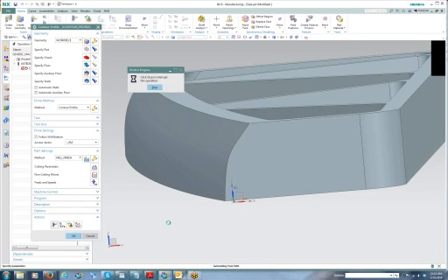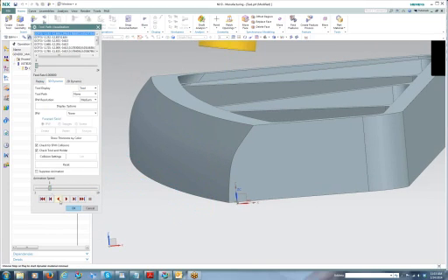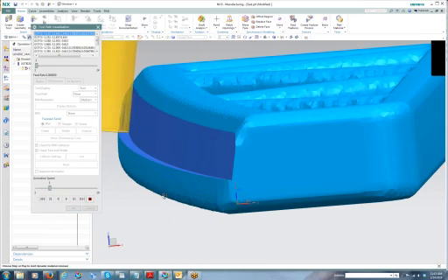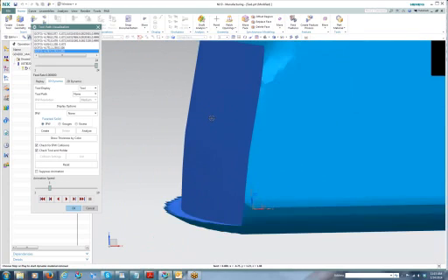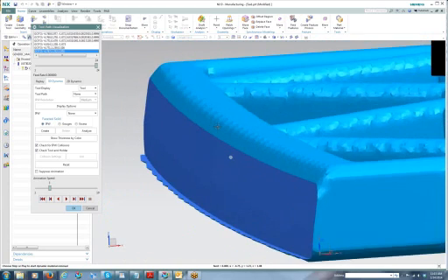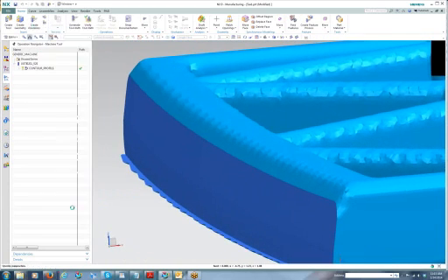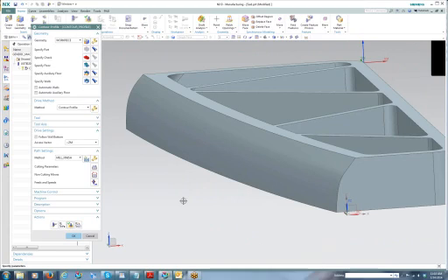So now when I regenerate, I get those same passes, but they're deeper down. So let's verify again. And you can see that the passes are now overlapping each other. So I've got a very smooth finish that's going to require just minimal bench work to complete. So that's a huge advantage, is this ring height machining we have when we swarf drive that is very easy to implement with just a few settings. And in many other CAM systems, it's very difficult to create a toolpath like that.